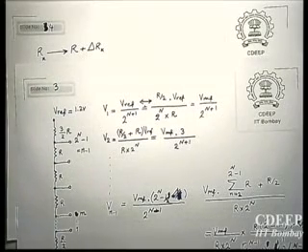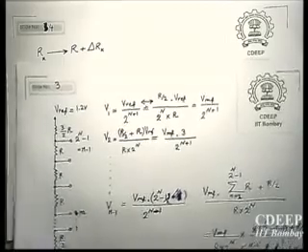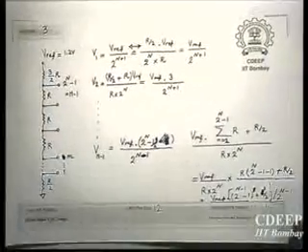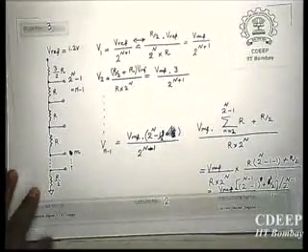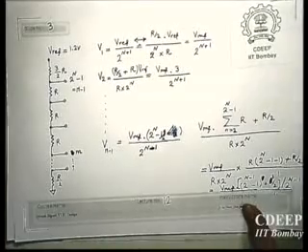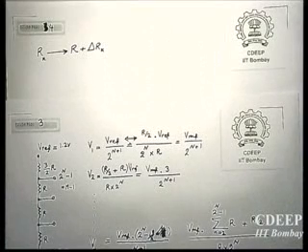See, you never need to calculate all details. Always you just consider what is the worst case. And then just you calculate what is the worst case value you will get for this particular design. Therefore, we consider what is the particular worst case mismatch, just delta R. And then for that particular mismatch, what will be the amount of deviation in reference values? Accordingly, how much nonlinearity we will get at the output of the ADC. So, I will stop it here. We will continue on Friday.